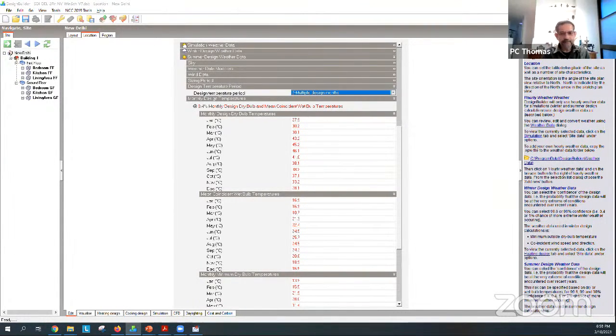That's very good. Thank you, Mansi. And you can test this using Design Builder. Correct. The only thing that I might add is that you can think about thermal mass being a battery. What Mansi just said is, if you're in a hot climate, you want the thermal mass to not get charged by the sun. So if you put insulation on the outside, you stop the heat on the outside and the thermal mass stays cool. The operative temperature will be lower.